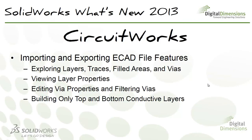There's been a lot of good enhancements added for CircuitWorks. You get a higher level of support with ProStep, IDF, and PADS files. And you can see a lot better representation of your files, including adding layers, traces, pads, filled areas, vias. Layer properties is all new, and you can see the layers in the board when it's being built in SOLIDWORKS. Via properties and filtering of vias, which are vertical through-hole paths, have been added to this release of CircuitWorks. And there's also a setting that you can show just the top and bottom conductive layers or show all of them.